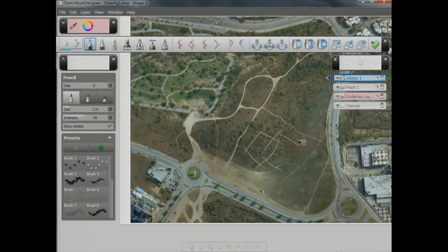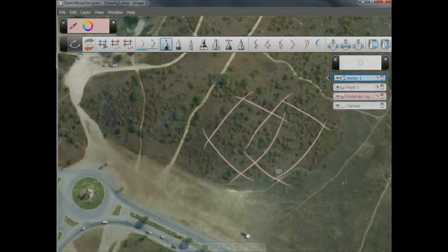And as you can see now, after we finish, we can tweak those things. So there are specific tools to grab the whole curve and just move it around because we have control over all the control vertices. There's this little icon there that lets us cycle through different options of different curves that will all share those 3 points. It could be a spline, it could be an arc, and it could be a segment. And we can do that with each of those, right? So this is exactly what I'm doing right now. Just going through, cycling all of these things.